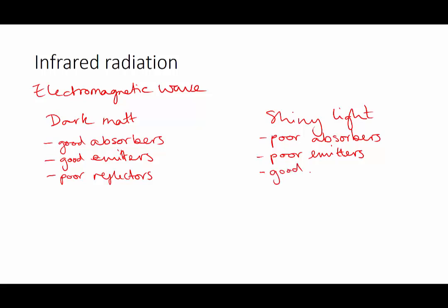So when you're answering an exam question that's looking at things with a light shiny surface or a dark matte surface, what you want to be paying attention to is where the heat transfer is coming from. Which object has more heat? If you are looking at the heat coming from within the object, for example, if we have an oven, then we want to know whether it's going to be a good emitter or reflector. Ideally you'd want the heat to be reflected on the interior to keep the heat in, and it to be a poor emitter on the outside.